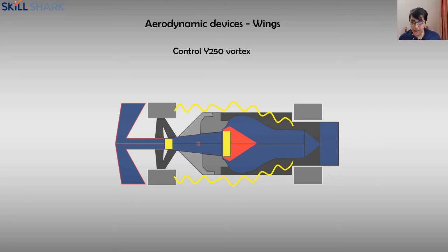So anyhow, what happens is you have a little vortex that gets generated over there, and then you also have vortices at the edge of the wings. And you can use that to your advantage. So you can see here that vortices get formed at the edge of these tires, and they go along the vehicle, and they get in the way of all these other components that are present on the vehicle. It makes for really bad airflow at the end of the day. Also, another potential risk is these vortices can get underneath the car and disturb the flow in the underbody, causing lift. Very dangerous, especially if you're going through a corner at a very high speed.